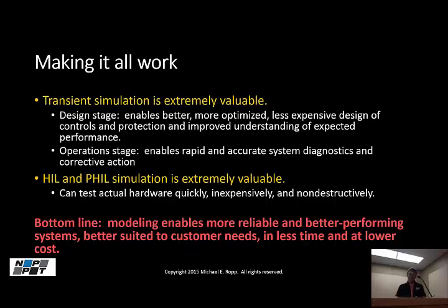Hardware-in-the-loop simulation then is where I can actually test real controllers with a simulated power system. And that can be valuable for bench testing, functionality testing, that kind of thing. We test relays that way. There's such a thing as power hardware-in-the-loop simulation, where you've got the actual inverters in there, and only the power system itself is simulated. We can't do that. We don't have equipment big enough to do that. They can do it at the National Renewable Energy Laboratory.